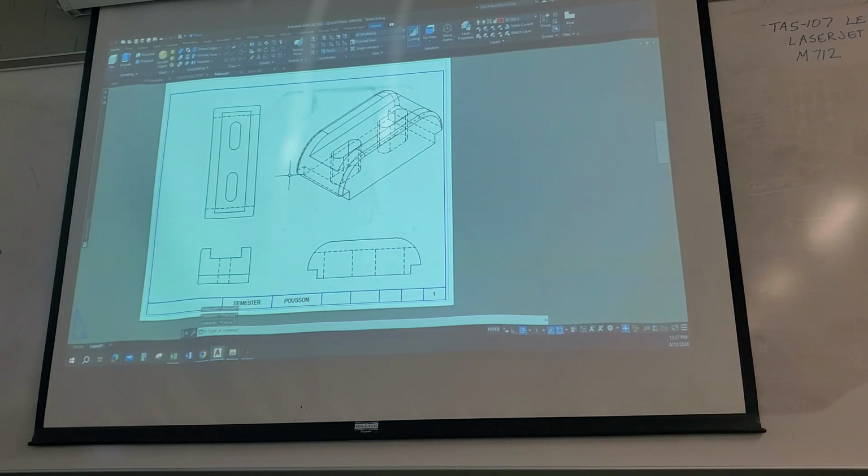Like I said, this one's sheet 1. Your other one, your 11 by 17 will be sheet 2. This one is called tailstock. And I've got it shown up here, representing your 0, 0 at the middle of that side. North, always on an isometric, so that'll orient it over there. But remember, do not show that north arrow. Do not call it plan view and elevations. It's top, front, and right side views in ISO.